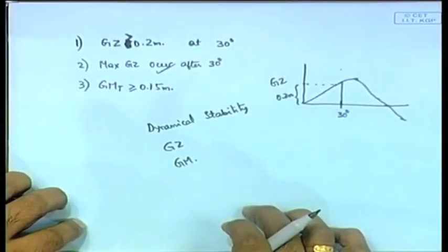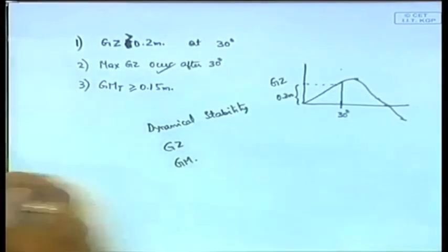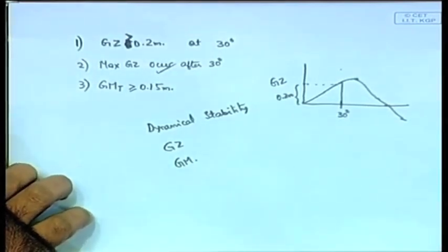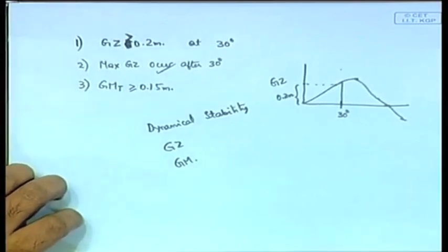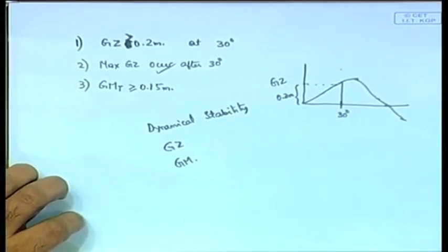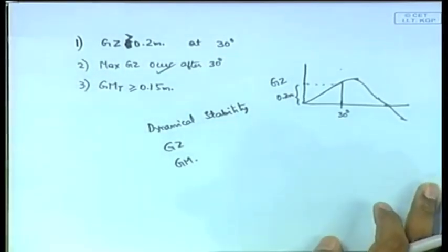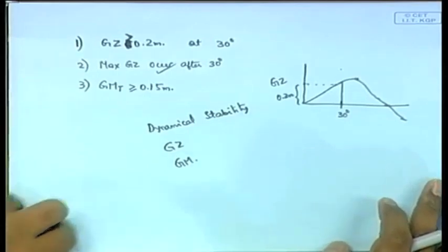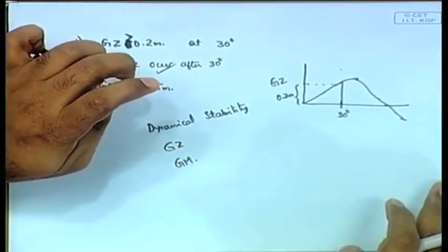That makes sense, but let me see. That's the basis for all the other rules. Which one is it? Maximum GZ. Actually, I need to think about this. I will tell you. That is a good question. The rule says that, so obviously there is some other criterion that I will tell you. Phi ultimate will be small if. Which one? Phi LT. What is Phi LT?